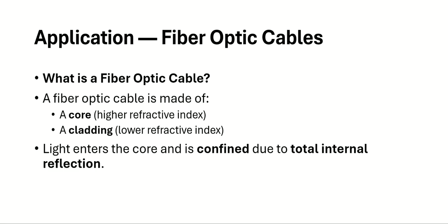If you leak the light, you get a weak signal, discrete signals, not continuous signals. So you're losing information pretty much at the point where you start leaking the light. You need the light to be trapped in the core, which has the high refractive index, to stay confined inside the core, and you get the max of the signal. Max of the signal, I mean as much signal as it can be.